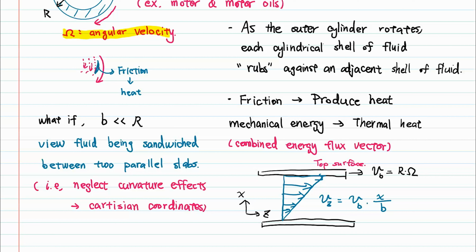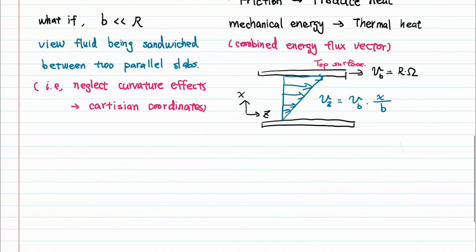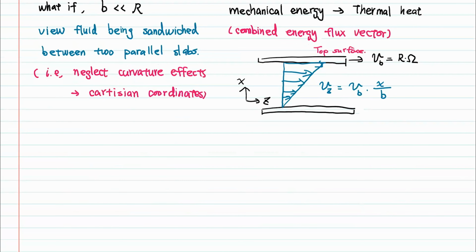Good. Let's continue. Here is the part where the shell energy balance should come into play. We're going to define a shell of liquid and perform an energy balance throughout that shell, using the combined energy flux vector.